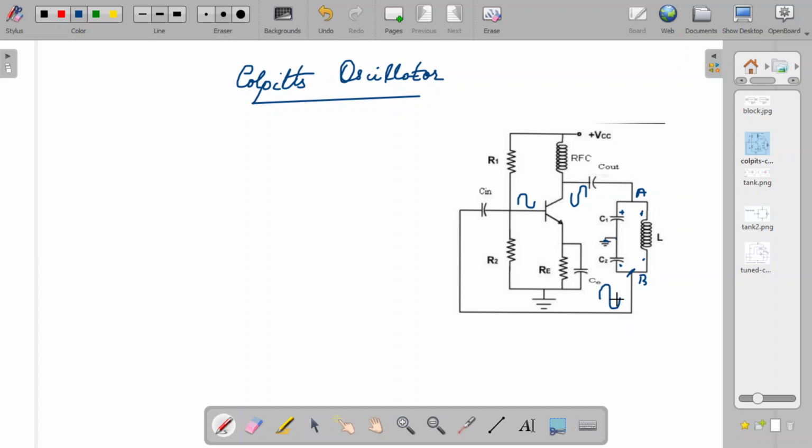Now you see this signal which is coming out of the feedback tank circuit, across V2, will be in phase with the previous input signal. So the feedback network here produces a 180-degree phase shift from the output signal, and thus you can get sustained oscillations in the case of a Colpitts oscillator. Okay, so this is how it works. Now we have to think about the beta.